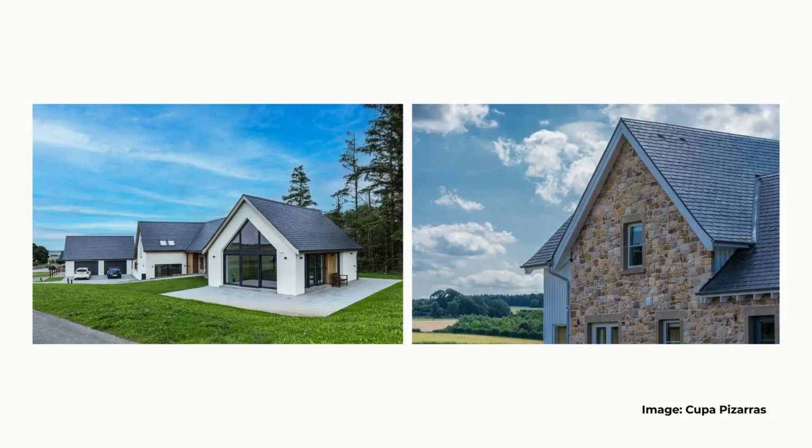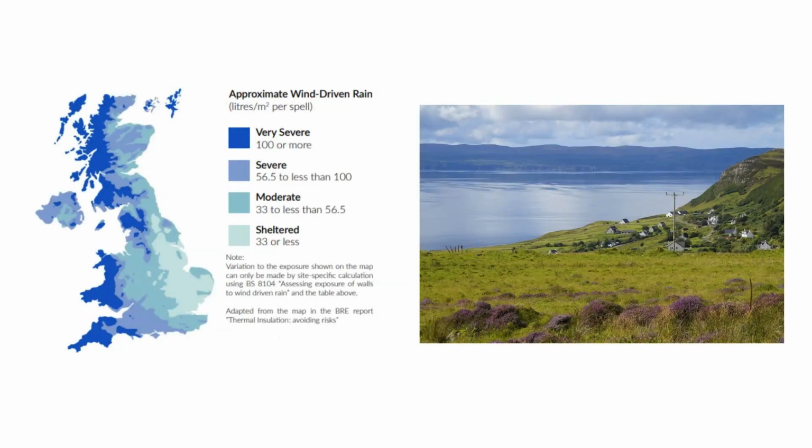One of the first considerations when designing a slate roof is the climate conditions of the site. The level of exposure a building faces from driving rain influences the required minimum lap specification. Additional factors such as tall buildings, dwellings situated on slopes or hilltops, and coastal locations may elevate the exposure rating necessary for a particular project.